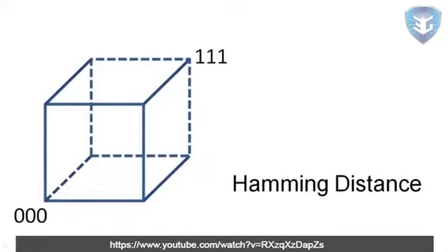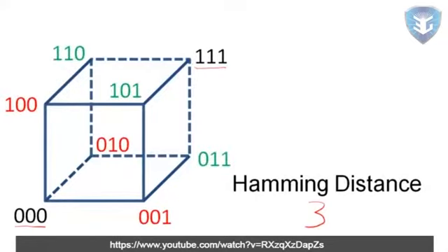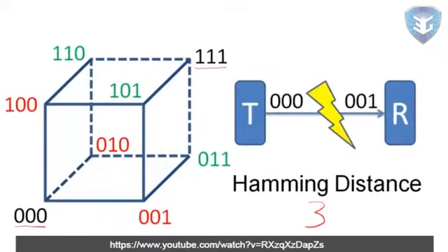If we add one more bit, we would have two valid code words whose Hamming distance would be 3, and a code with Hamming distance 3. We would also have 6 invalid code words. In this situation, the receiving component could still detect if an error occurred in one bit. But now, because the erroneous word has a Hamming distance from one valid code word that is less than the distance from the other, we can correct the error.